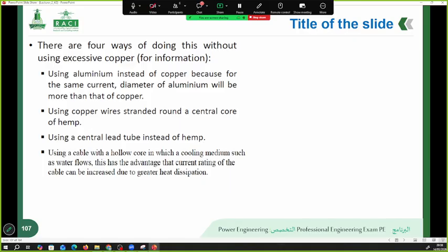This can result in a high current density, which can lead to overheating and potential damage. Therefore, for low and medium voltage cables, the conductor diameter is determined primarily by the consideration of safe current density, rather than minimizing stress.